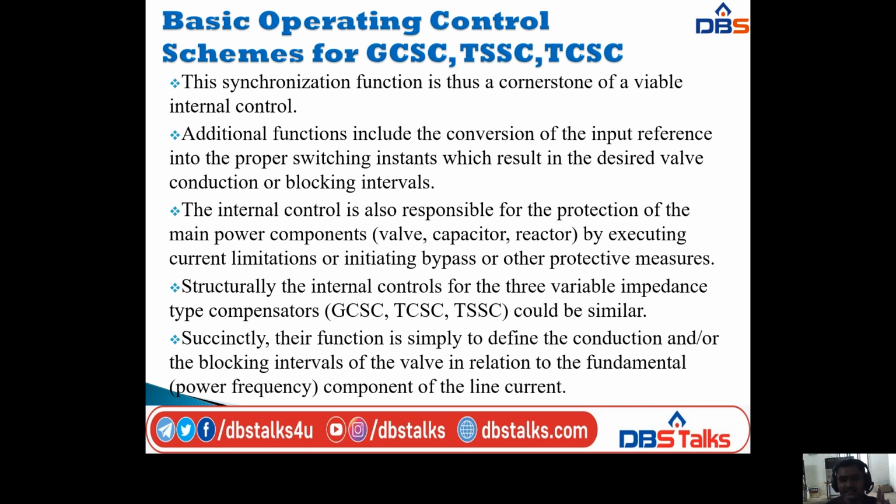Structurally, the internal control scheme for the three variable impedance type compensators, that is GCSC, TCSC and TSSC, could be similar. Their function is simply to define the conduction or blocking intervals of the valve in relation to the fundamental component of line current.